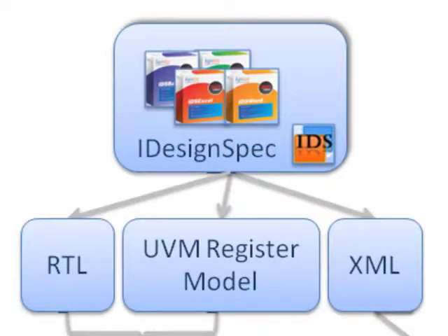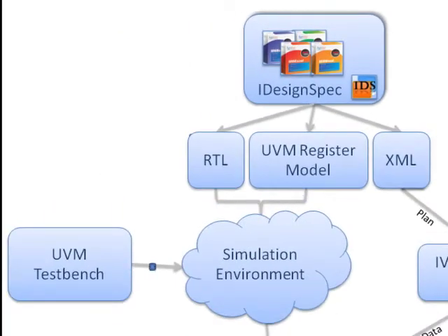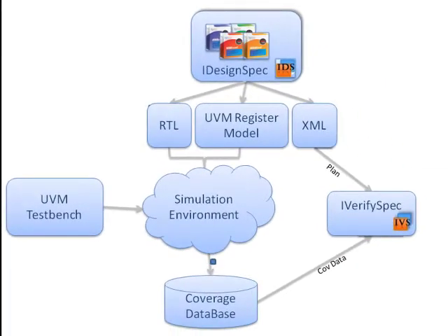IDesignSpec converts hardware register specifications into many different outputs, such as RTL, UVM, and XML. These files can be simulated in a UVM environment using any vendor simulation tool. A coverage database is generated, which is used to ensure verification completeness.